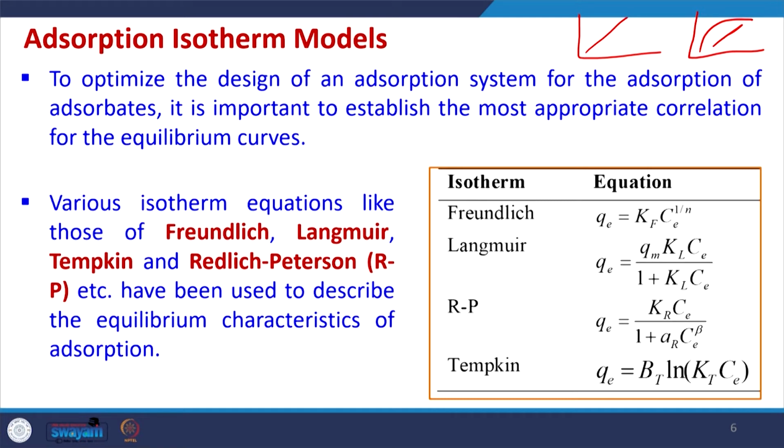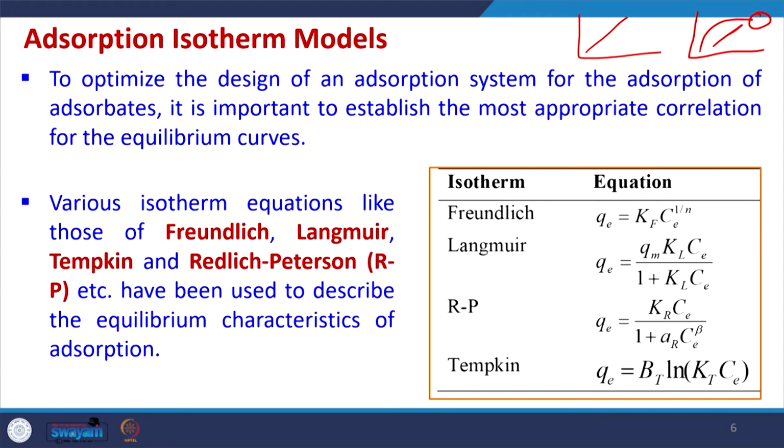So, this is possible. Without equilibrium data we can never design a system. This is the first thing. So, we require equilibrium data for any unit operation to design, and if it is mass transfer controlled, this is possible. So, we require these isotherm models which actually represent the equilibrium data at that temperature to optimize and design any adsorption system.